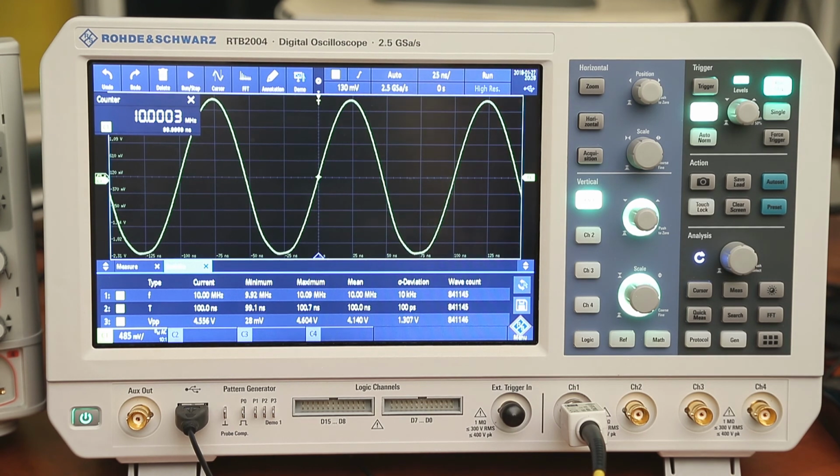But I just find that when you look and compare the display of the two, this is easier to read, and because of the larger real estate on the screen, it's just clearer and easier to read. The Keysight, by the time you put on the statistics mode, it just gets a little bit garbled, although I do like the fact that the Keysight tends to keep the normal measurements down the right hand side of the screen away from the actual signal area, but of course then the signal becomes smaller. But the screen of the RTB is just bigger.